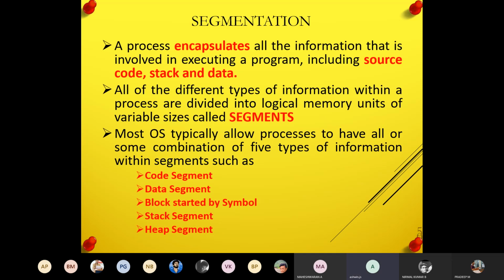So segmentation, like I said, is also dividing a memory into different sizes. So they will be segmented into a code segment, data segment, block started by symbol, stack segment, and heap segment. The code segment is nothing but the code which I'm going to write. So I will make it available only for the program. Likewise, if it is data, I will provide some memory for the data. Likewise, I will provide the remaining also.